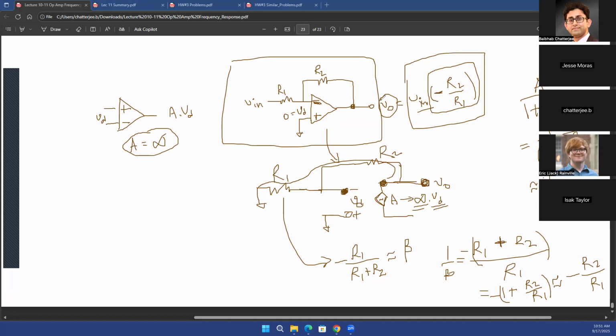That is why the op-amp's output voltage is not zero, even if you have a virtual ground property, which means at your input, the differential voltage is zero. That's because your op-amp's output is already fixed by other quantities in the circuit. It's not fixed by the op-amp. And since the output is fixed and the op-amp's gain is infinitely large, op-amp's input has to be zero.